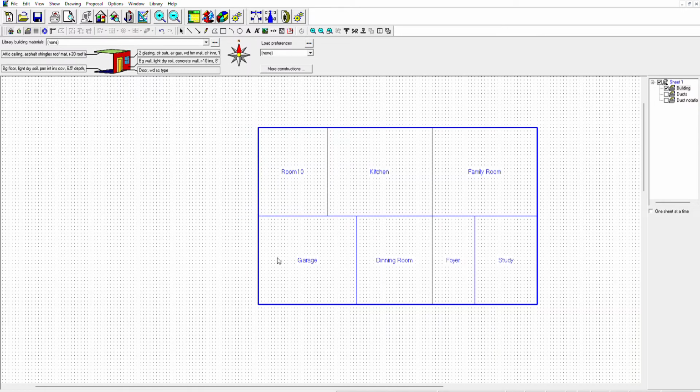So this is one of my most favorite tools: merging rooms. You click here, you click the other room, and you hold shift, you click both, you select both, and you merge rooms. Oh, how beautiful is that? Okay, so now we put garage. It's a big garage. All right, and also you can move these letters by holding shift and then clicking on the name, garage.